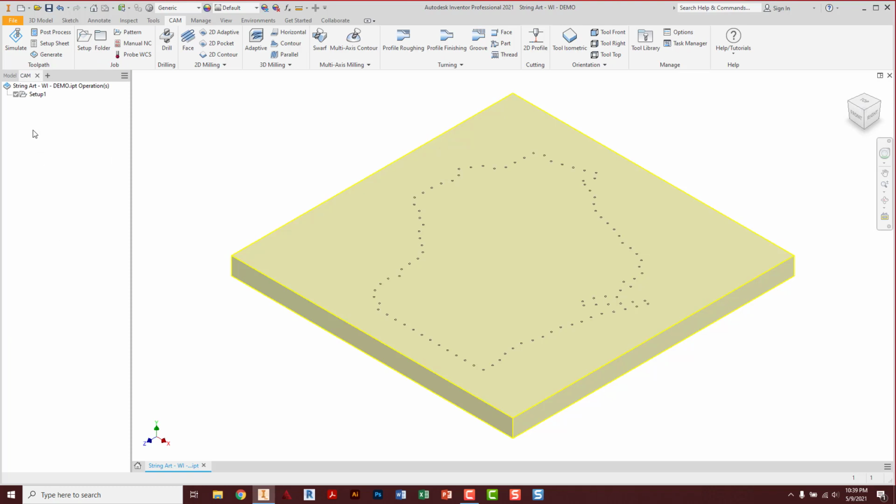So that first step is doing a setup that tells the machine how big our material is. And if I just click anywhere in the blank space of the browser, there we go. That was weird. Had to click on, click off, but that's just a way to turn off the highlight that the setup was still doing. But click back on it. There it is. At any time, you can go back and check your XYZ, that it's the right direction, the right location. Click off to deselect.